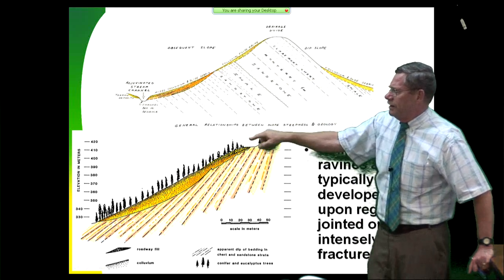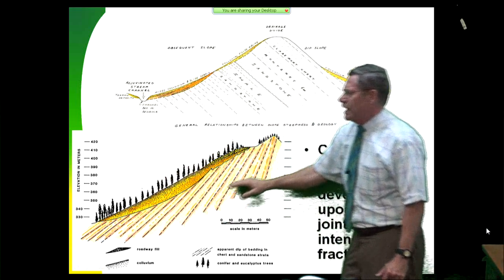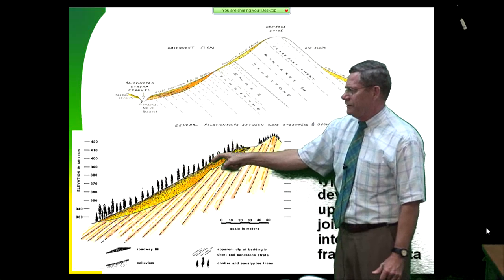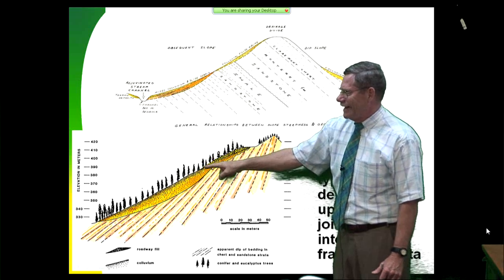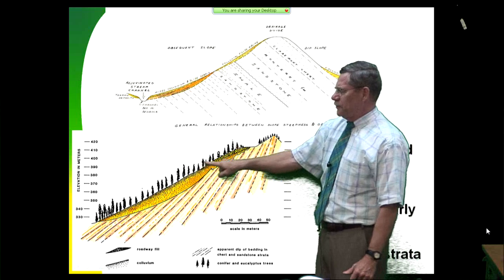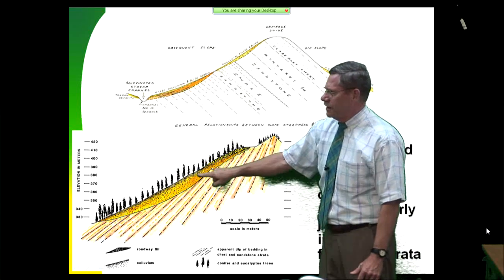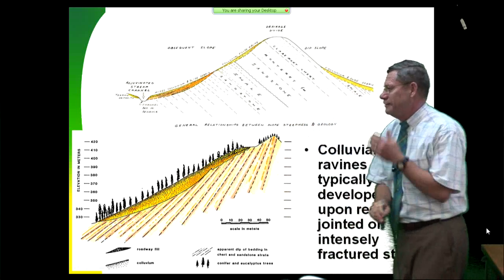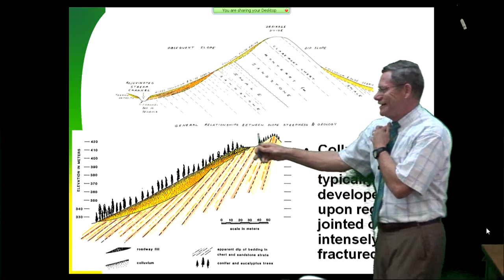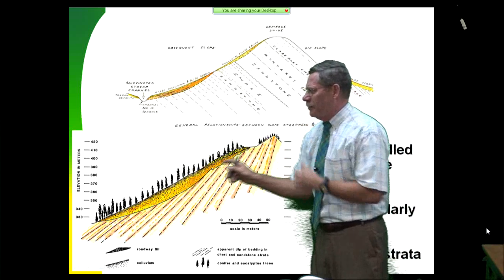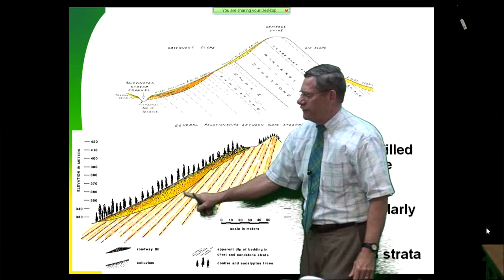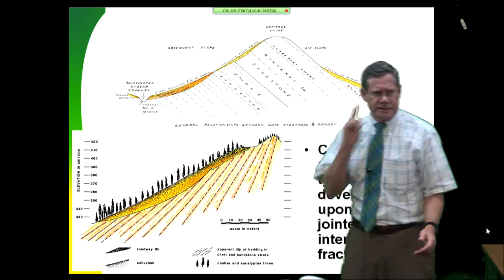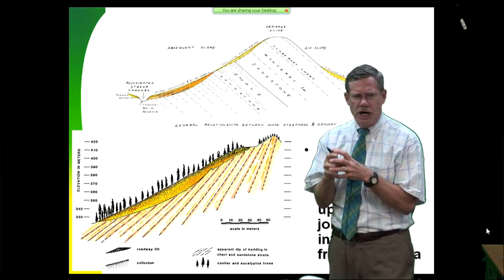Steeper. Right here is a case I had for City of Oakland where we had a culvert right here, and the culvert came down the hill about 150 feet and discharged right about here. And in one storm, January 3-5, 1982, this culvert dug a hole down here 47 feet deep, much to everybody's shock, including me. And we went out and started drilling on this thing and probing around, and what we found was we had a huge colluvial-filled bedrock ravine in here, and the phi angle of this material was all 45 degrees. That's gorgeous, clean, hard chert.